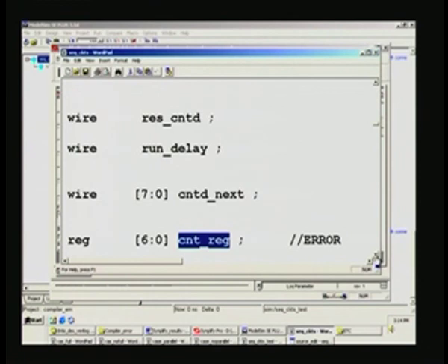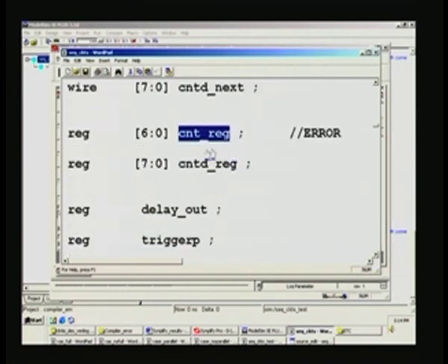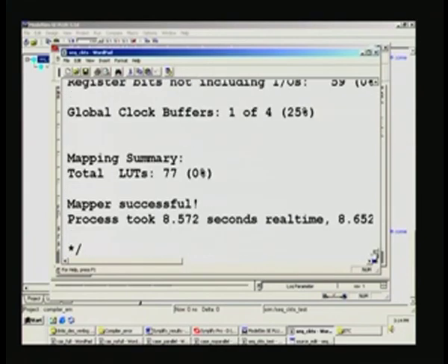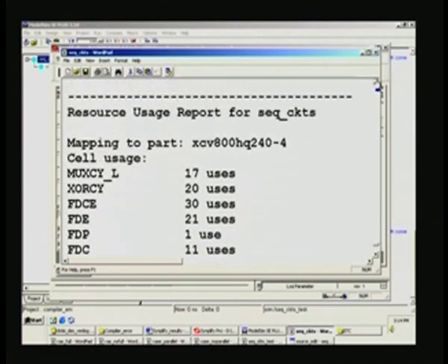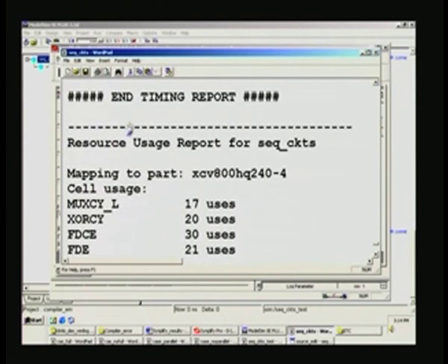And before we wind up this error creation, we will consider one last example, and let us go to the very end, and you see here. Another point is, once you have done all this, it is a good practice for you to copy relevant details from the Simplify results and place and route results into the same source file as a ready reckoner.